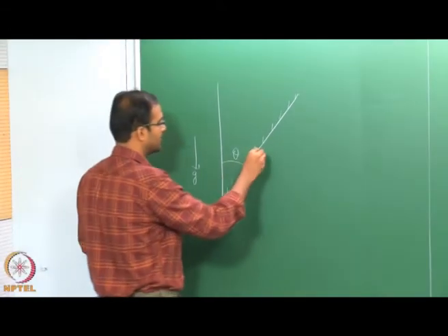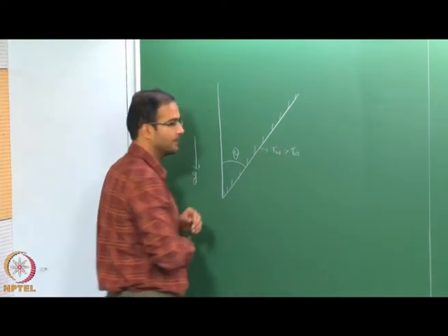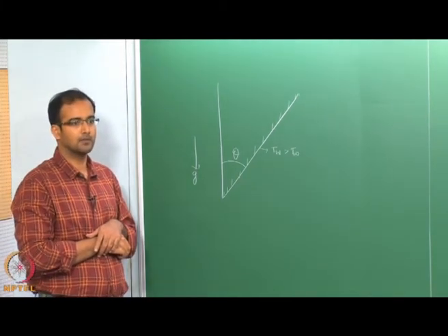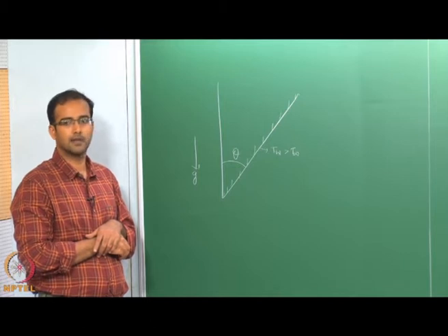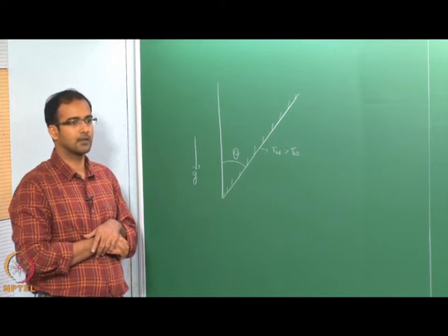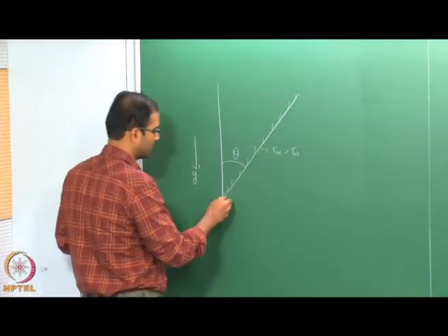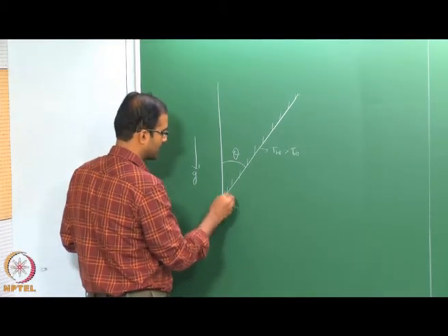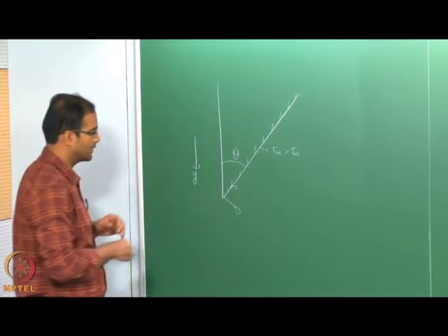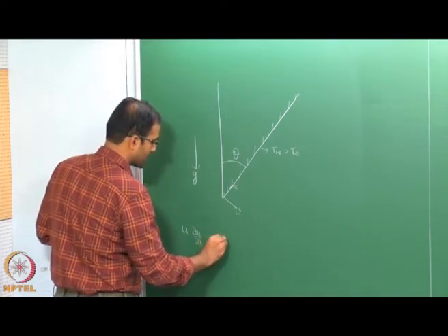So, this is the tilt of the plate facing downward. So, if you heat this plate such that T wall is greater than T infinity, still the same natural convective boundary layer will form, but the only difference is the strength of the gravity will be slightly reduced in this case. Okay. So, the same governing equations will be applied. For example, if you denote this coordinate as x along the plate and perpendicular to the plate as y, you can still write down the momentum equation.